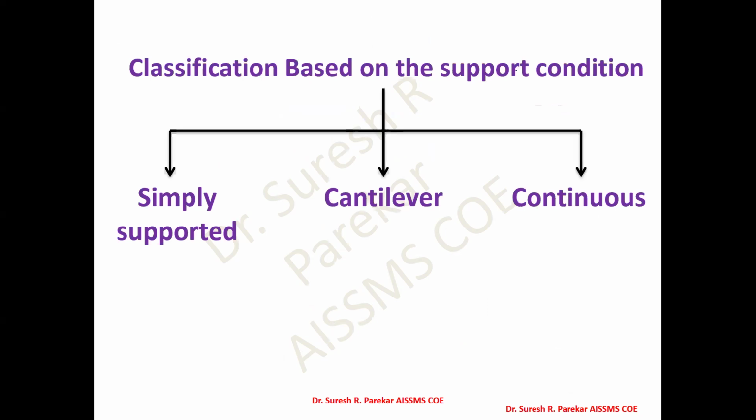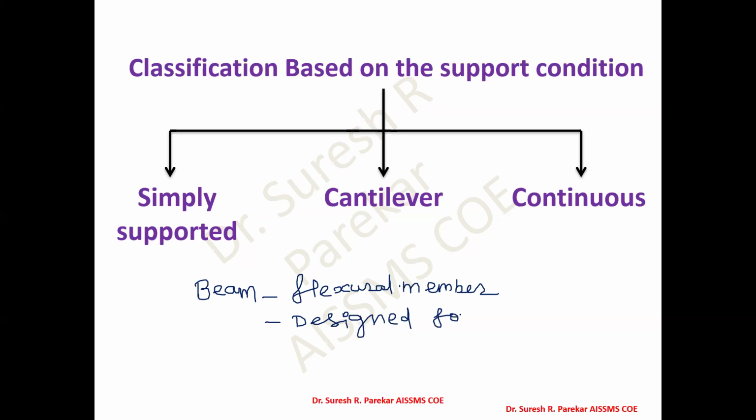Now, we have to be very clear that a beam is a flexural member, and therefore it is designed for shear force and bending moment. As for a column, we are generally designing for axial force, so it is an axial member.